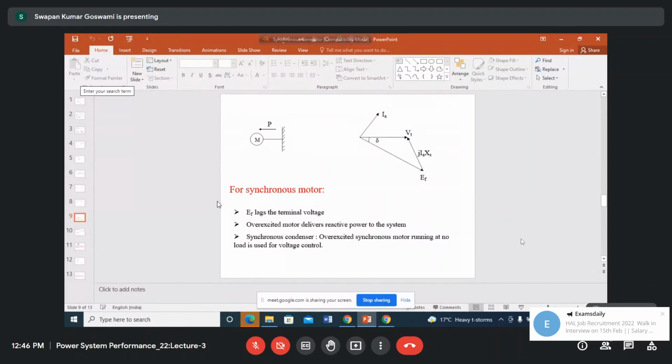Already we have mentioned that active power control is possible only from the power station, because we need a generator. But reactive power control is possible from almost anywhere. From power stations, the generator can control reactive power and voltage. You can install a shunt capacitor, or a synchronous motor, anywhere. If a synchronous motor is installed that can deliver reactive power, it can also participate in voltage control.